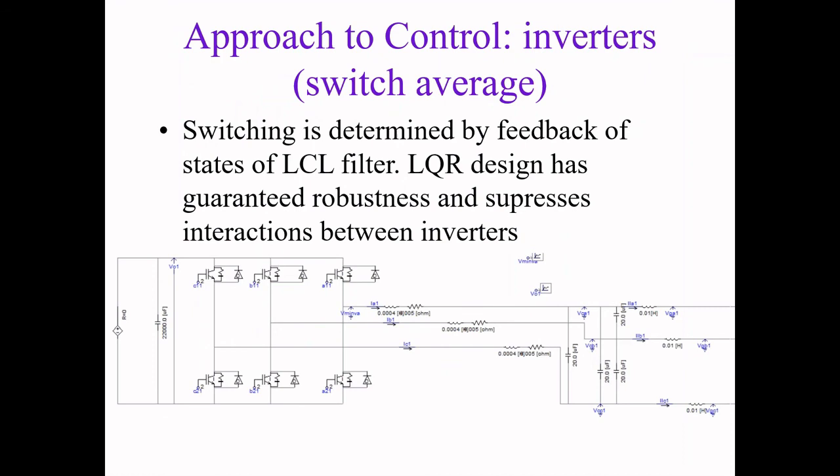So this was a phasor level of interpretation, and it gave rise to this idea of a line drop compensation type of correction, and it just does help. Now when we get to talk about specific inverters, we're trying to say, well, this is a three-phase inverter, and yes, this will switch high or low to produce the voltage on this particular phase. The switch average approach says, however we control it, this will then set some sort of average voltage on A phase coming out of this inverter, an average voltage for B and an average voltage for C.